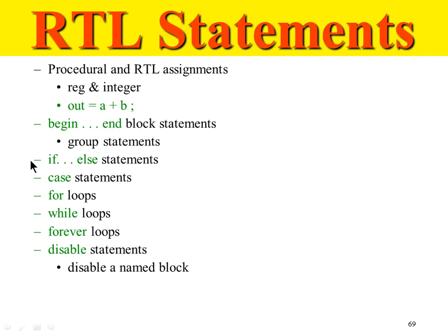Then there are certain conditional execution statements like if, else, if conditions. There are certain things called case statements. We'll see some examples of this. Like any language, we'll have for loops, we'll have while loops. There's something called forever loops. Forever loop is something that's used only in test bench for simulation purpose, because in hardware there is nothing called forever. It works with respect to inputs.